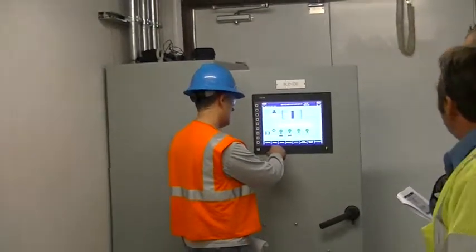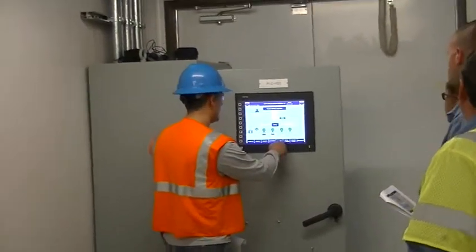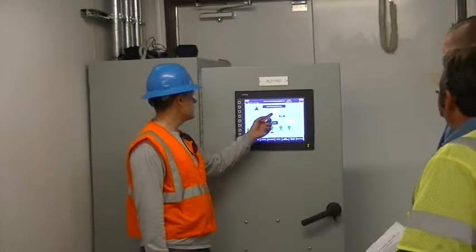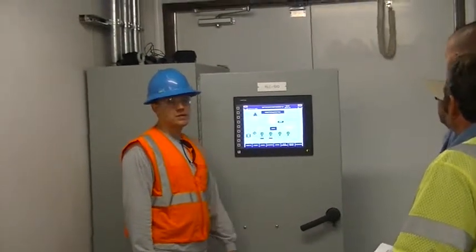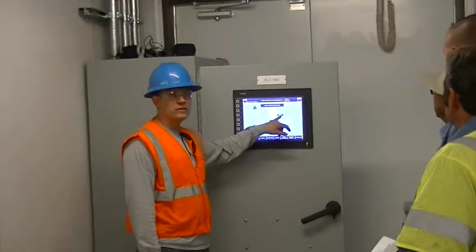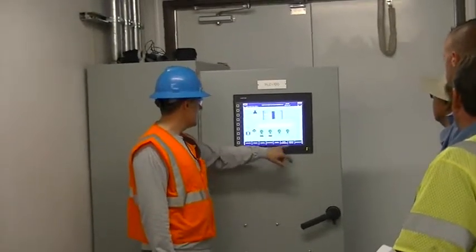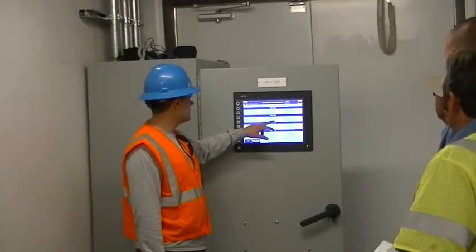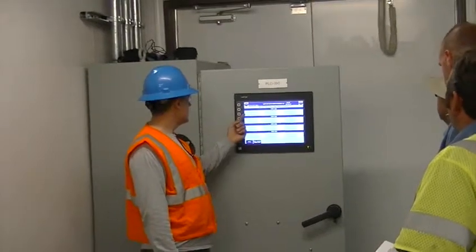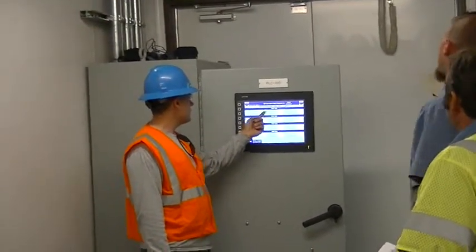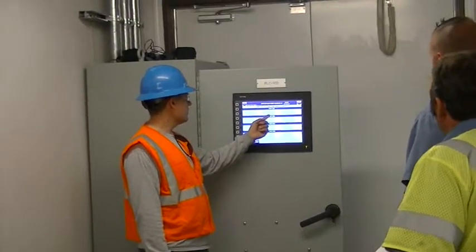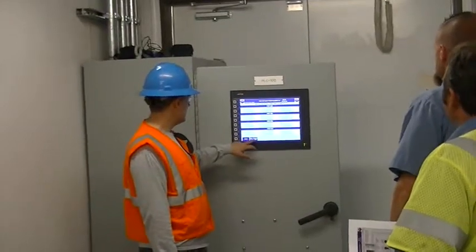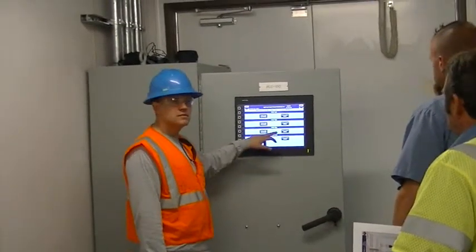So let's go to the flow totalizer. The flow totalizer is just a pop-up. It'll give you your hourly, your daily, your monthly, and your total. And it has a reset button right there that you can use to reset it back to 0. Then we have our run times. So you have your pump 1, pump 2, pump 3, and pump 4. It'll tell you your total motor starts, your run hours. This is your daily starts, your daily run hours, and that's the previous day's starts and run hours. And you can reset those with these buttons.